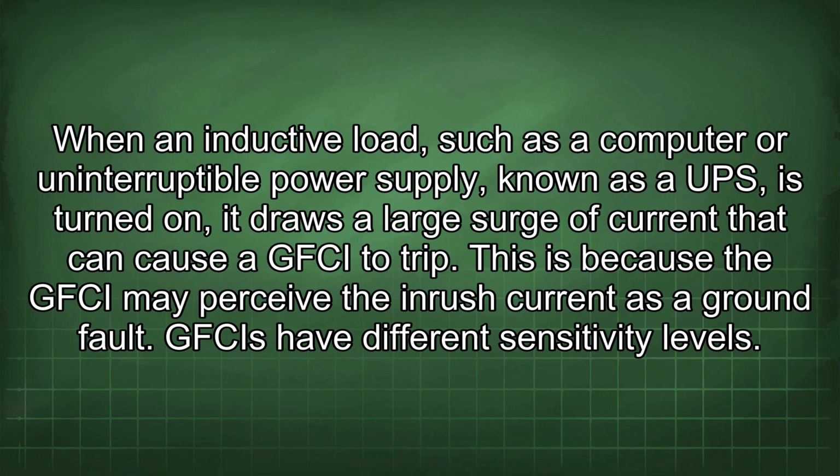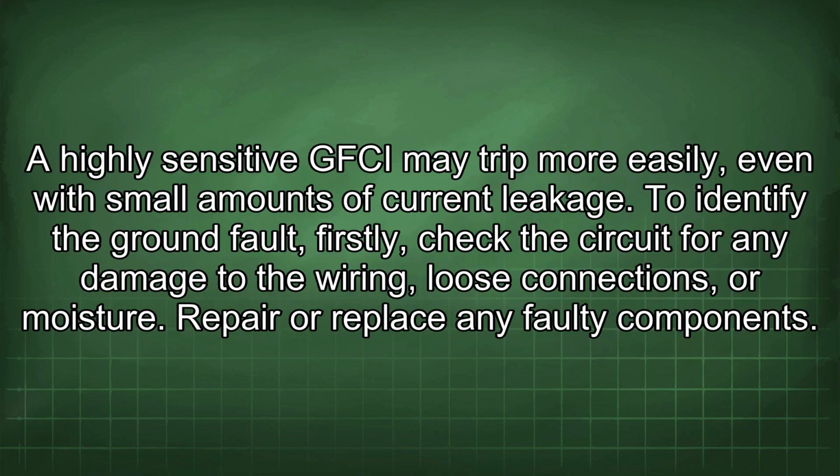GFCIs have different sensitivity levels. A highly sensitive GFCI may trip more easily, even with small amounts of current leakage. To identify the ground fault, firstly, check the circuit for any damage to the wiring, loose connections, or moisture. Repair or replace any faulty component.